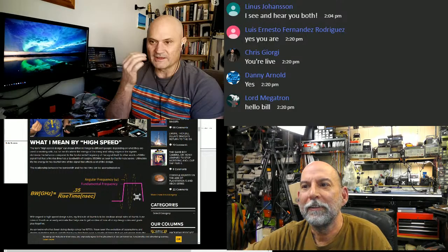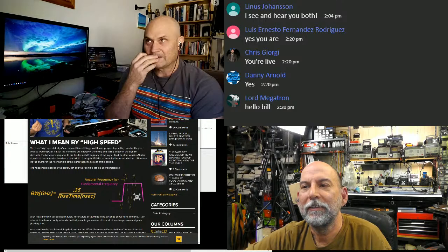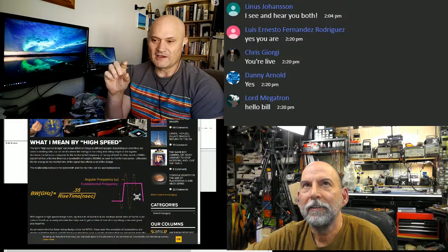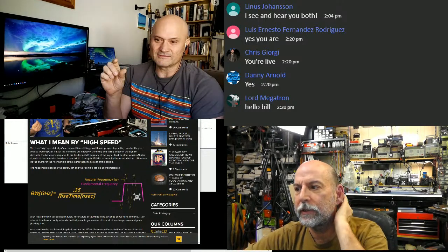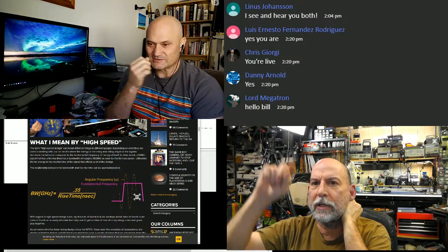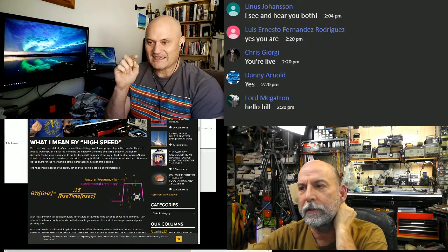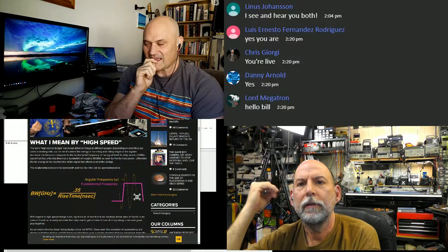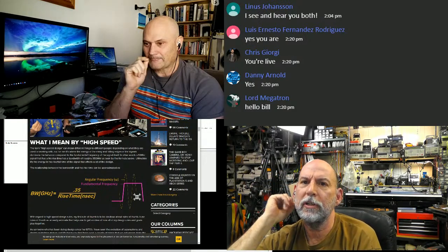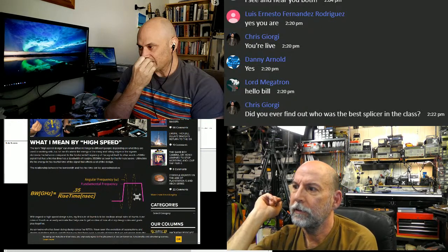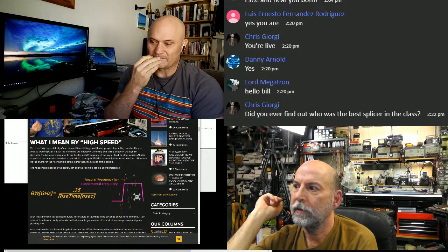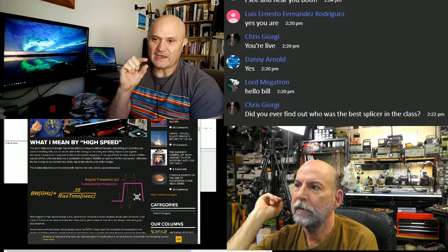But the terminator was always a load between the signal line and ground, which you call parallel termination. Half of a parallel termination. And true parallel has a signal to VCC and to ground. Yeah, right. So that's another way to do it. But if you have an unbalanced single-ended line, you put a load on the end that's matched.